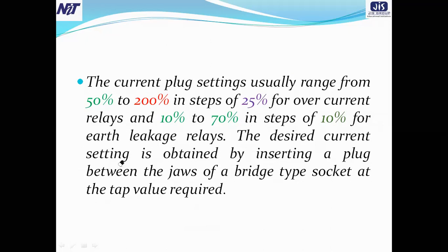The desired current setting is obtained by inserting a plug between the jaws of a bridge type socket at the tap value required.